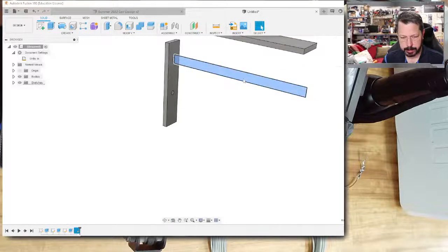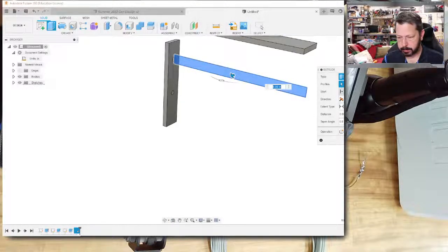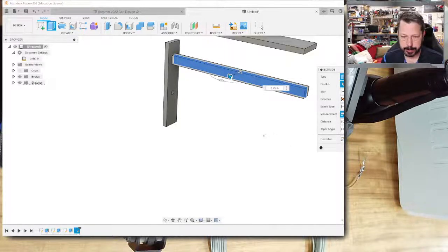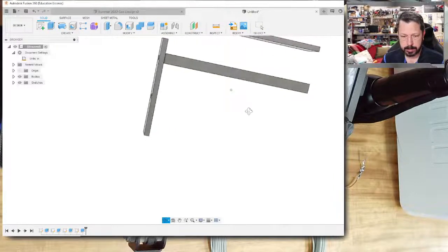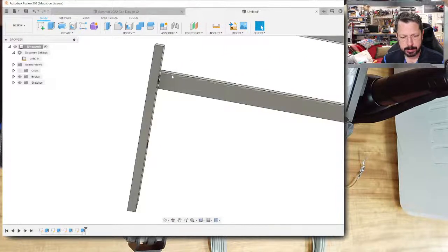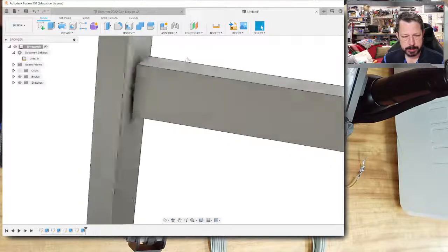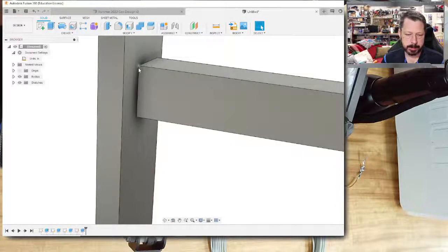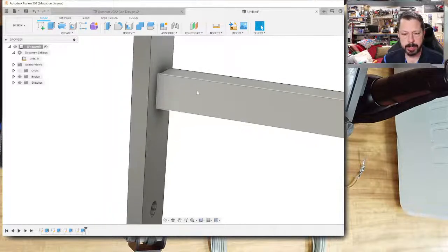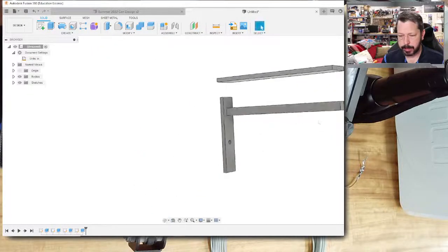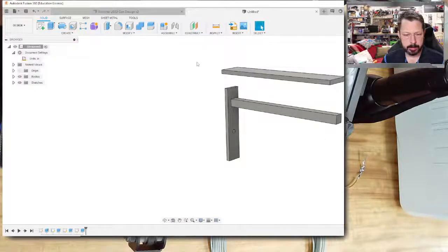And then we'll extrude this in both directions. 1/4 inch. Oh, not two sides symmetric. Two sides is if you want them to be different directions, you know, one side 1/4 inch, another side 1/2 inch or something. So now I've got this little thing. I didn't want to connect it to this surface. There's probably a better way to do this, but if you connect it, then they become one part, and I need two separate bodies. So we could make all those that we wanted if we wanted to have those in there. All right.